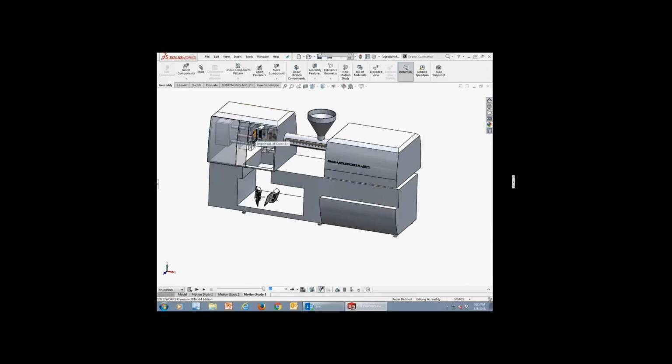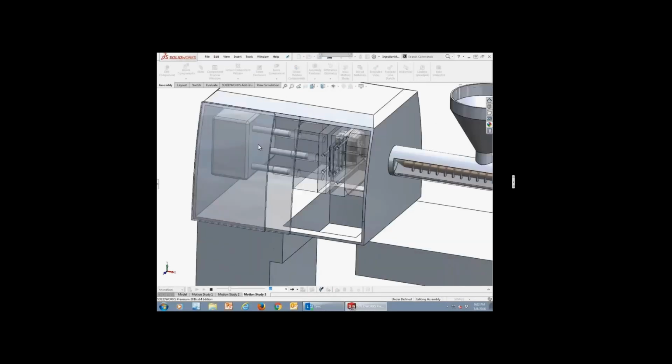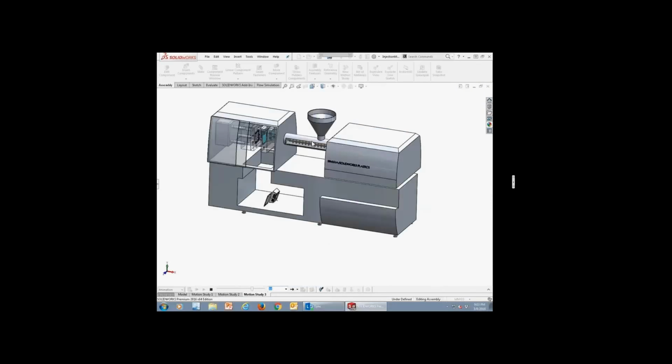It's almost like a cake. To make a cake, you have the actual cup or the cavity where you put the batter and bake it, and you get the cake for that shape. Very similar. This mold has the cavity, so plastic gets injected here, and then there's cooling liquid going around it, and once all the plastic is injected, it's also being cooled. When it's not fully cooled yet, it comes out. It's still a little hard, so it doesn't deform. And then it ejects it out, and it just cools outside. So this is a typical injection molding process.